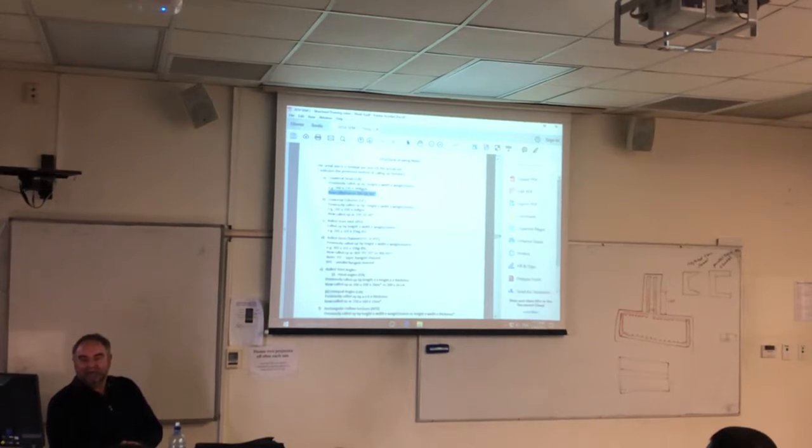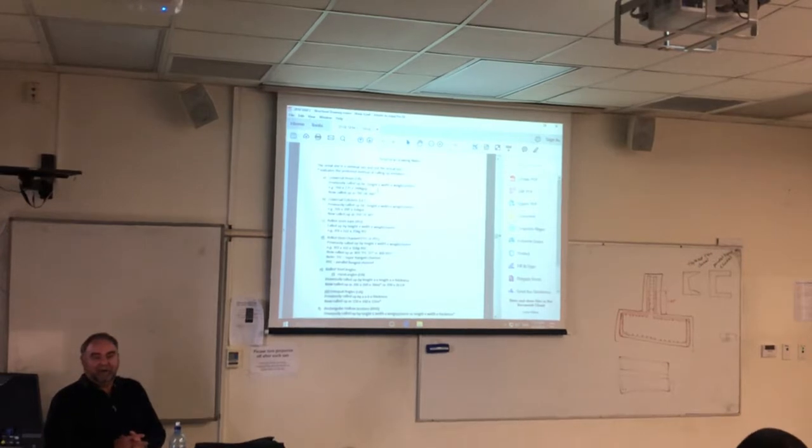You've got to have a look at it, think about it, and do it the way it should be. So if, for example, my beams are called up as 760 by 270 by 244, I would like you to pull that particular beam up as 760 UB 244. Right? You might find there's nothing like that. That's fine. I might have pulled them up the proper way.